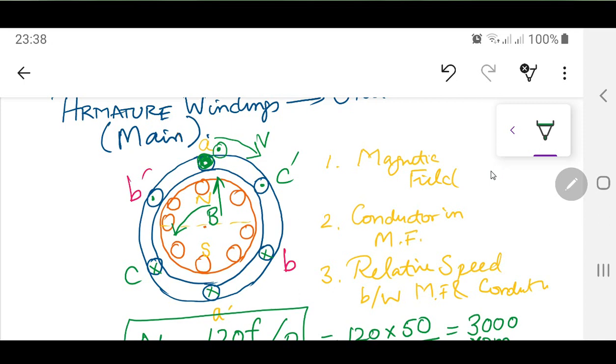and the rotor is actually an electromagnet. So you are going to apply some like 1 ampere or 2 amperes of current to the rotor, and on the stator side A, B and C phases you are going to get approximately an output, depending upon the number of turns on the winding and how they are arranged. They are certainly going to be double layer windings over there. I'm not going to go into details of the winding designs over there.